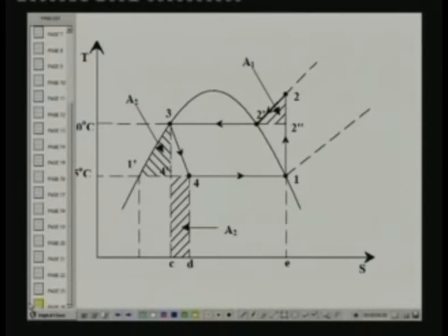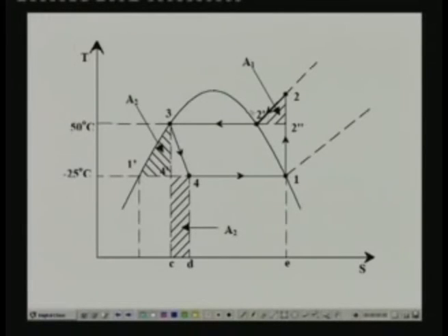So, I will quickly explain how we can calculate this superheat horn area. Process 2 to 2 dash is an isobaric process, that means P2 is equal to P2 dash, and remember that we know all the entropies and all the state point properties. So, area under the curve 2 2 dash is nothing but integral TdS from 2 to 2 dash.